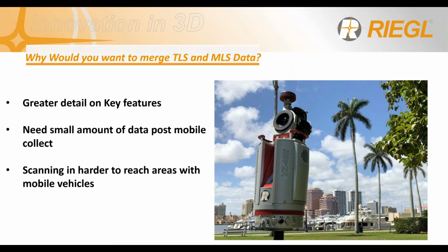And third, a terrestrial scanner is going to be able to get into a lot more areas that a mobile vehicle can't reach. I'm thinking about those underpasses of bridges where maybe you aren't going to be able to drive, or a field you're not going to be able to get your vehicle out to, or a trail. The mobility of a terrestrial scanner when you're carrying it is going to be a lot greater than where you can actually fit your vehicle. So sometimes they fill in these needs where we need them to.